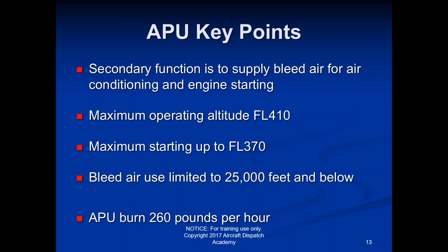I always think it's kind of funny because they just don't understand that the bleed air that was being used for the air conditioning, when you go to start the engine, has to be taken for that. You've got to shut off the air conditioning system so that it's not drawing any of that air, and all of the air that was coming out is being redirected to the engine so that it can start. Then you notice it starts up, and as soon as they get the engines back running, they hit the air conditioning packs buttons and turn them back on, and all is good. But for that 30, 45 seconds while they're starting the engines, everybody's freaking out.